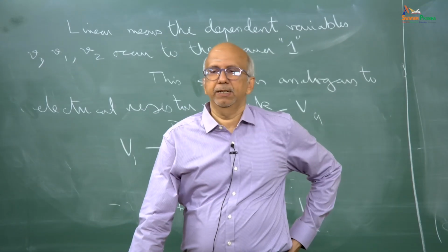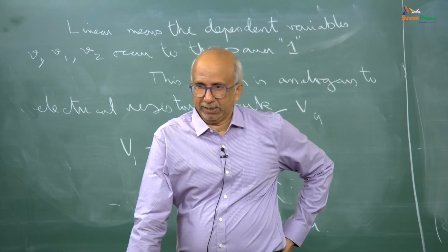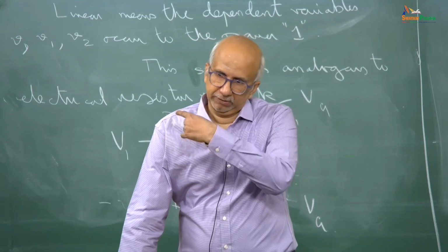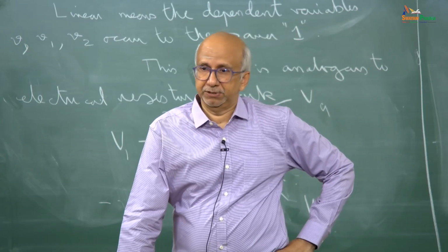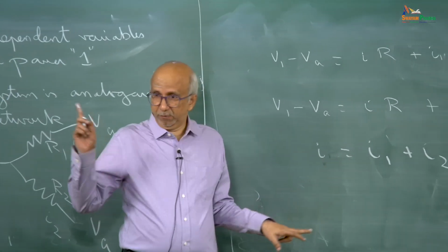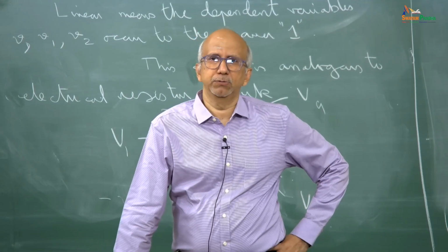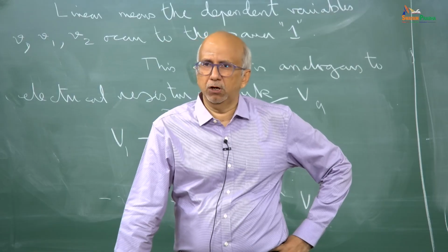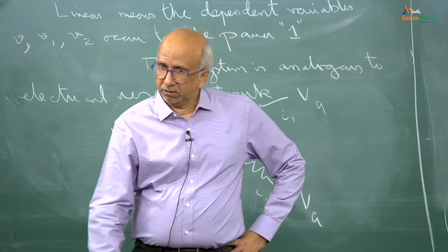Only thing is the current here is not velocity, current here is the flow rate. The equivalent of current is flow rate, not if you had current density then you have to multiply by area. In the velocity problem I multiplied by area because I was doing mass balance, which involves balance of flow rates, not balance of velocities. Okay. So, this is like flow rate, velocity was like flow rate per unit area. Okay. So, anyway, these are things you have to think about, and the point is again we made an assumption here that Ohm's law is valid, and only because of Ohm's law we are getting a linear equation. If Ohm's law is not valid, then you will get a nonlinear equation.